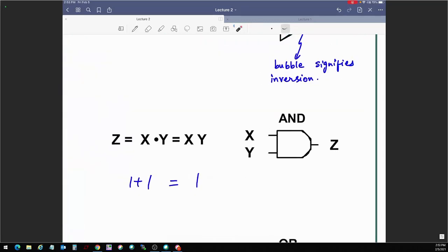For AND, it is sort of a D. X and Y are your inputs going in. Z is your binary output variable. Now, because you have two inputs here, again, you can have 0, 0 or 0, 1 or 1, 0 or 1, 1, right? 4 possible combinations for the two inputs, given that X and Y are binary. And for each of those 4 combinations, you will get a particular 0 or a 1 for the output Z. And because this is AND, Z is only going to be 1 when X and Y are both 1. So big D is your symbol. And the way you write Z is, say, X and Y, or simply XY. And like I said, you can also have a 3 input AND gate with inputs X, Y, Z, and then you can call this F of X, Y, Z.